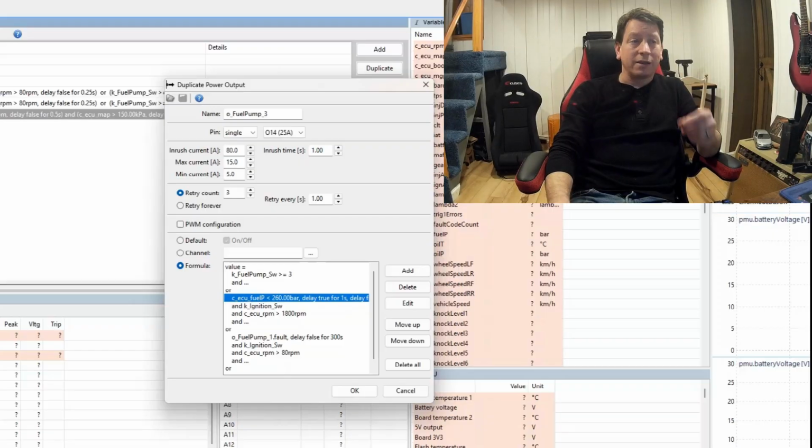And if you tune like that, that 1 second drop in fuel pressure isn't going to cause a problem as long as you have enough injector overhead. That's also why we recommend giving yourself some injector overhead. So I have room to add 20-30% injector and not go lean. So this will help save it, and this will be smooth. This is a great way to turn this on.